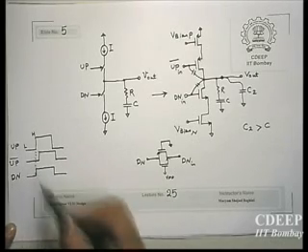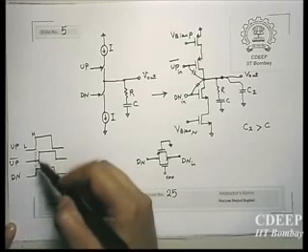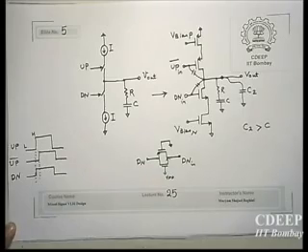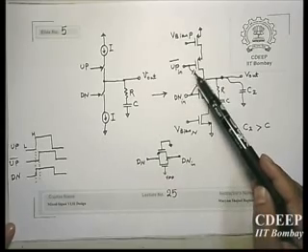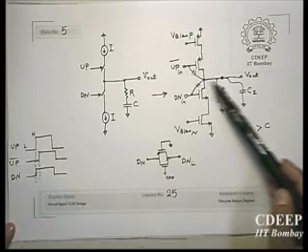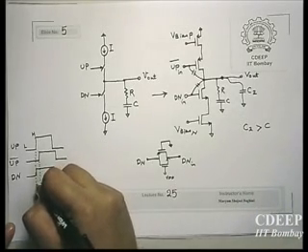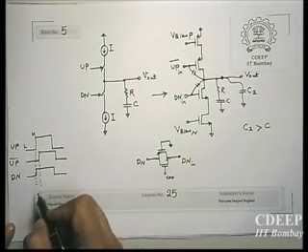So now here what happens is, if you look at this duration, up is high, so therefore up bar remains low and down is low. Therefore you will get some additional current that you don't expect to get. A source current, but you don't expect to have it. So during this duration, you will get an additional I source because up bar is low.